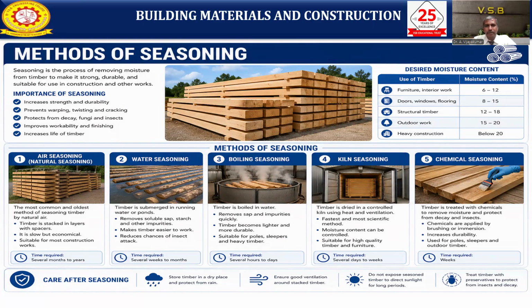What moisture content should be present? For furniture and interior work, the moisture content in the timber is 6 to 12%. For doors, windows and flooring, it should be 8 to 15%. Structural timber is 12 to 18%, outdoor work is 15 to 20%, and for heavy construction work, moisture content should be below 20%.